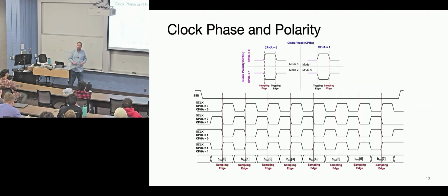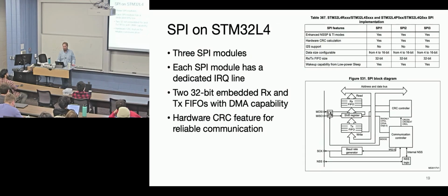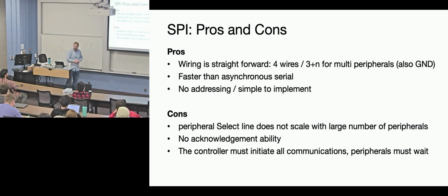What about this horrible, overcomplicated slide? So this one, we have these different clocking polarities. You have 4 different possible modes, and this means that your clock could be positive or negative, clocking in on the rising edge or falling edge, so 4 different modes. You can imagine that data may be misinterpreted by one peripheral who is expecting one mode versus a different peripheral. Maybe because the data format is different between them, you'd want to separate those on different buses. Any other exciting reasons? I like the clock one. I didn't think about that one.